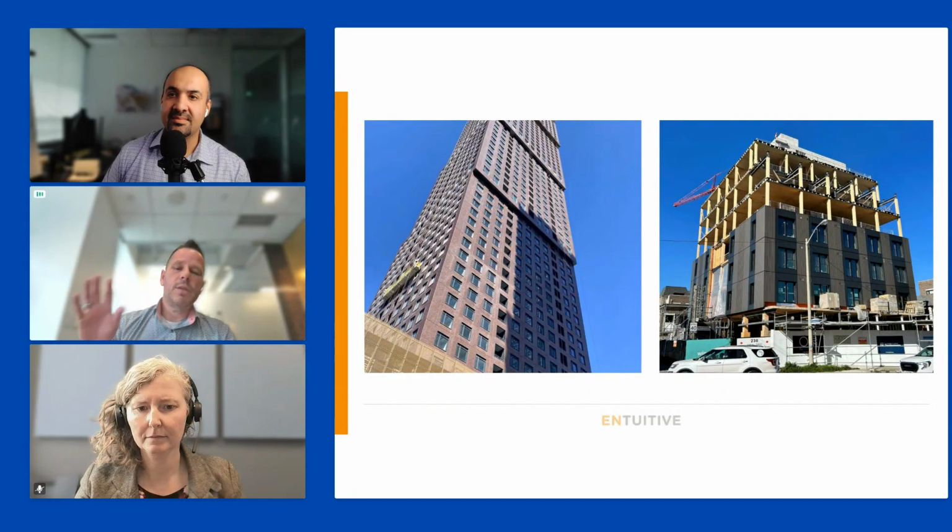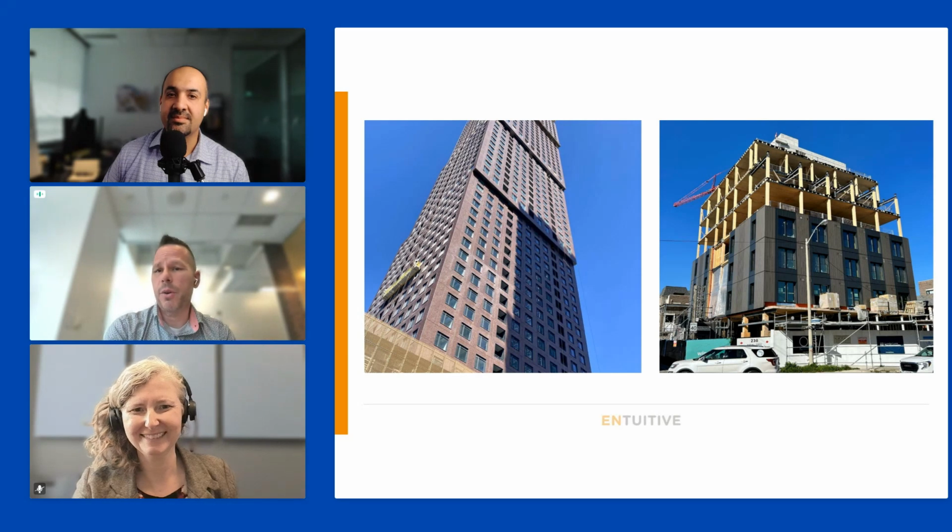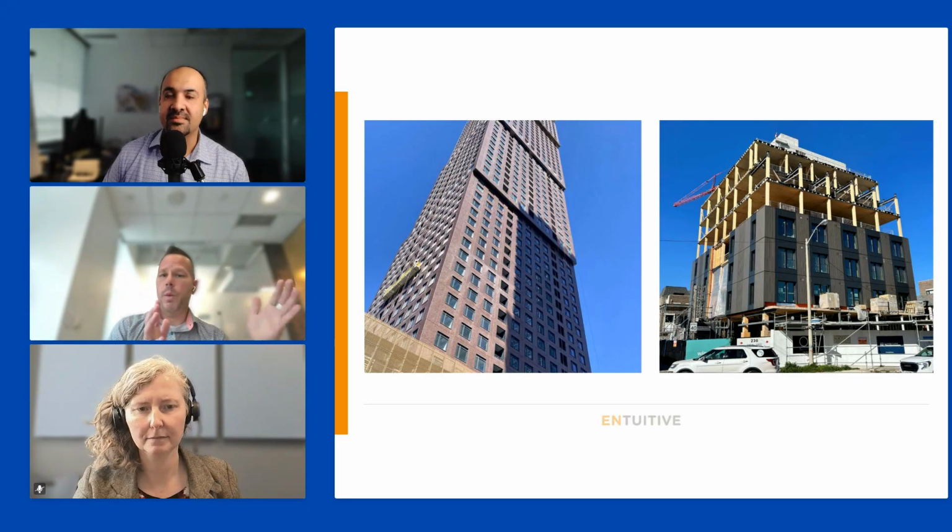Okay, so what do these kind of highly performant wall systems typically look like? I have a couple of examples here. One is actually one of Pam's and Kara's projects, 230 Royal York Road. This is a mass timber building, but I'm really intrigued by this building enclosure. It's a mass timber panel assembly with exterior insulation, thermal cladding clips, attachment clips, and then some exterior cladding. These are triple glazed fiberglass windows.